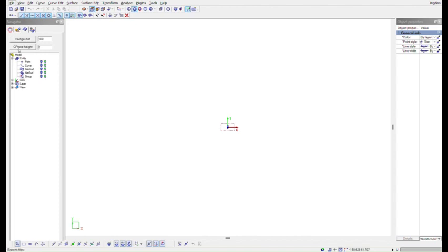go to file and import 3D model. You can use a 3D model or image here, but I'm explaining 3D models. Then you will browse in the file browser, where you can select the 3D model. I will select one of these, the lion. If you are going to open a DXF file, then the extension should be selected here. And if you are going to open an STL file, then you have to select it here, and then it will show us the STL file.